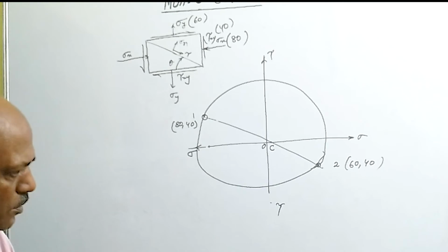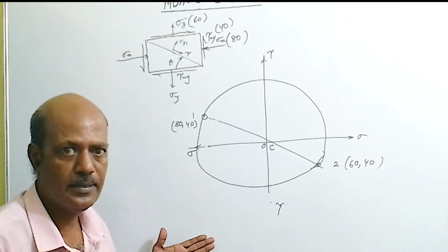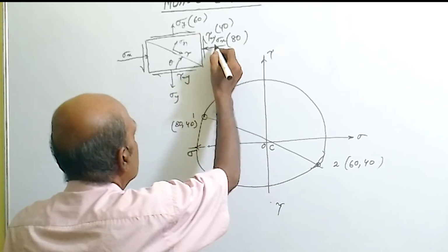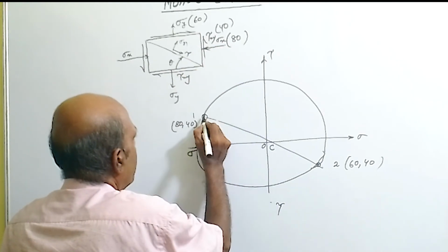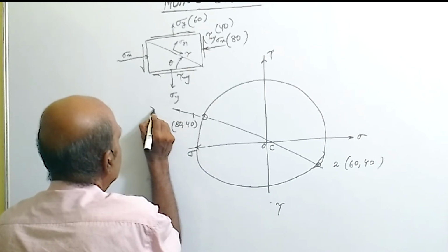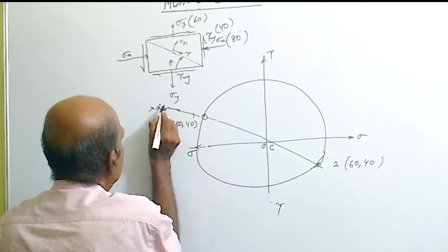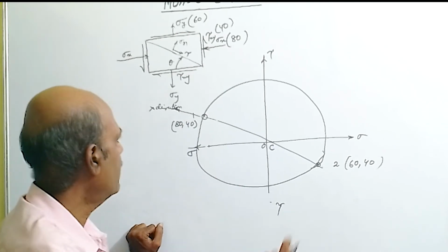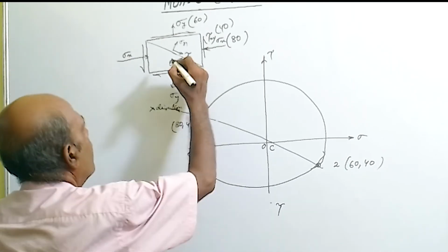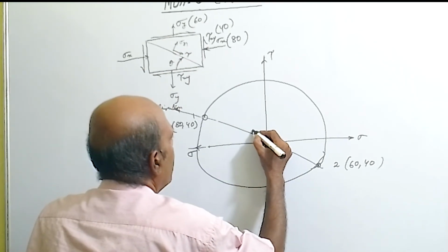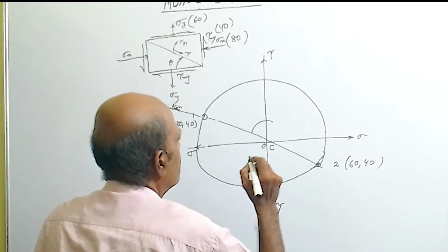Now you find where the x direction is. So here the x phase point is plotted at this point. So this will be your x direction. Now rotate the x direction by 2 theta angle in clockwise sense. So from here you measure this rotation.